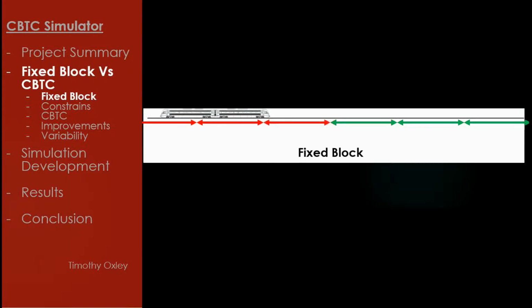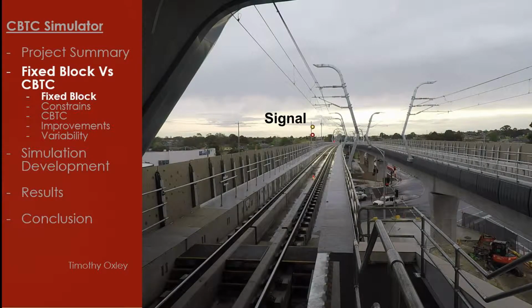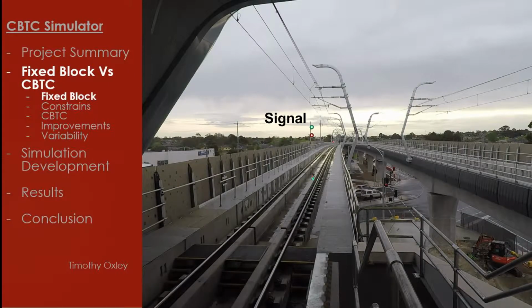Circuits which sense the presence of trains within a block feed the logic controllers of the signalling system, which do not let a train enter a block unless the track circuits have proven it to be vacant of any other trains. At that point, the signal at the beginning of the block will turn from red to green, allowing a driver to proceed into the block.